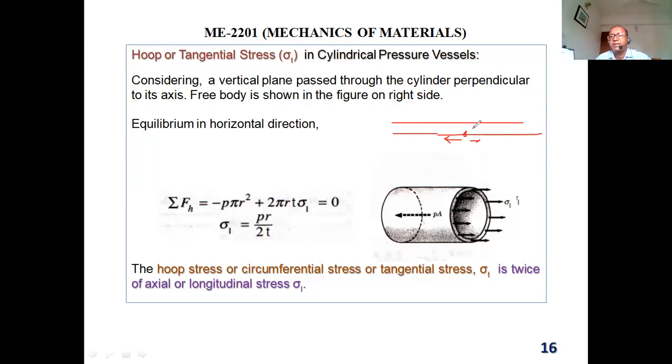And how do they test it? They pressurize the cylinder with water or air, then hold it for, say, 2 minutes or 1 minute. If the cylinder is weak, then it will burst and the pressure will suddenly decrease. That's why they test it. Like when you take it to Navana or Southern, whatever their service center, they do it in a similar way. They clean the cylinder, then they pressurize.